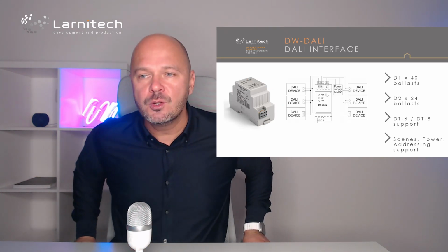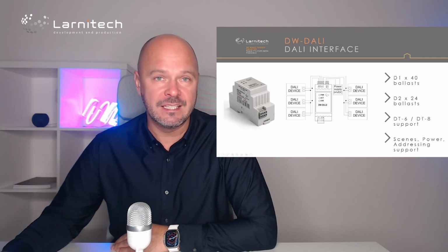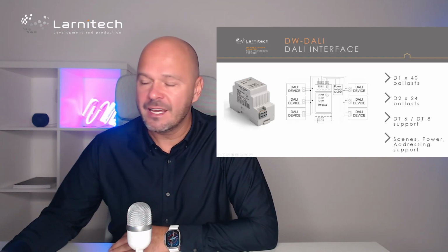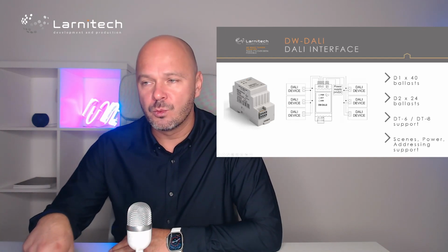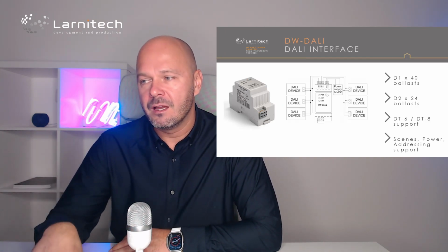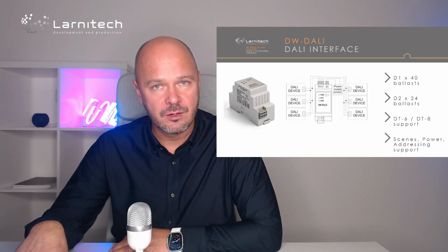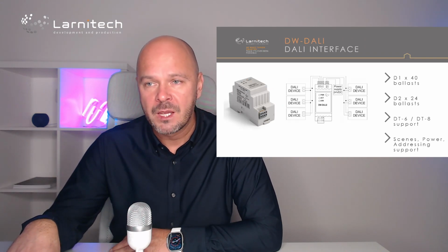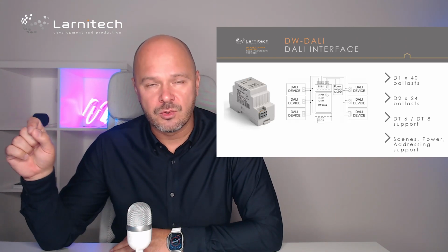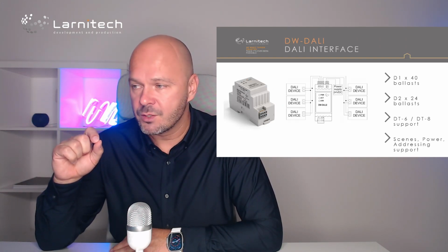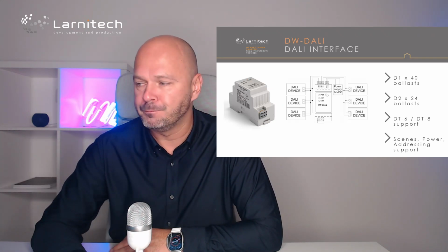But there is a new type of address inside DALI, which is named DT8. This DT8 address has inside all the information which is needed to dim one normal light, or maybe RGB, or maybe RGBWW, where the temperature of the white light will also be controllable. So you will be able to use it also. We now support it too.